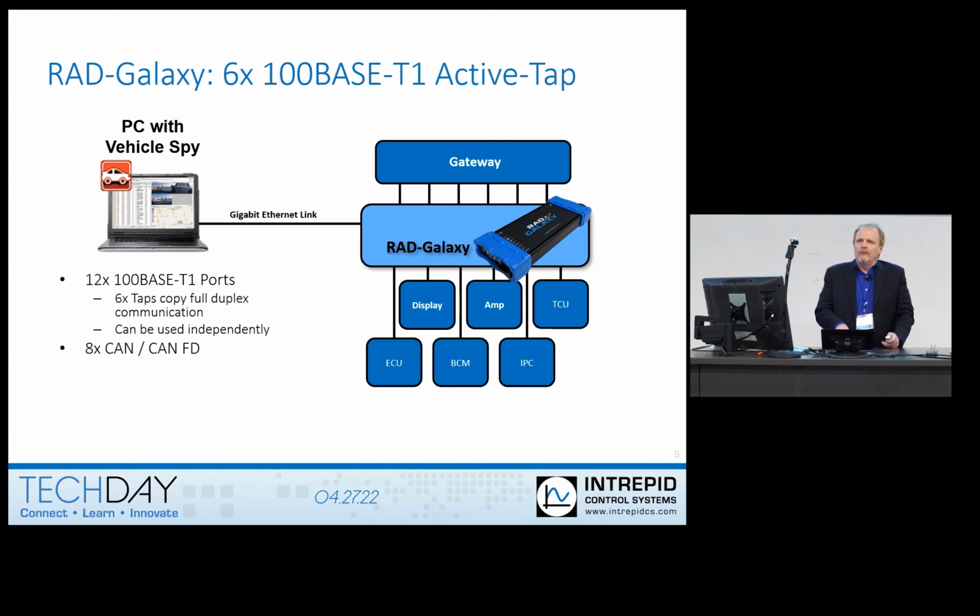It also has some legacy networks built in to log CAN and CAN-FD. So this is also logged at the same time base as all the Ethernet networks. So you can see correlation of events on one network and what correlates with events on another. It also supports diagnostics over IP. Automotive voltage ranges from 4.5 to 36 volts. And it does include a standalone data logger in the form of an SD card.